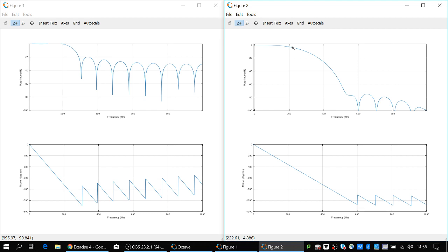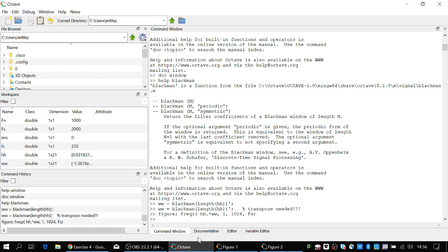We fix the width. So if transition bandwidth is now 300 hertz, but should be, say, 100 hertz, then we need to have wider window.